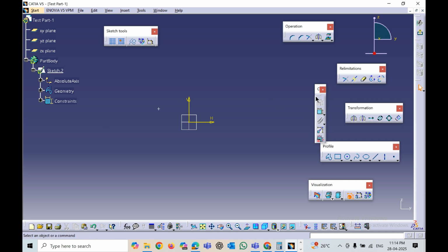see, why I can't create the dimension is that I have deactivated these visualizations and options. So now the dimension, we can see it. In case you can't see any of the dimensions, it means that the dimension constraint option inside the visualization toolbar has been deactivated. So just select on it, and